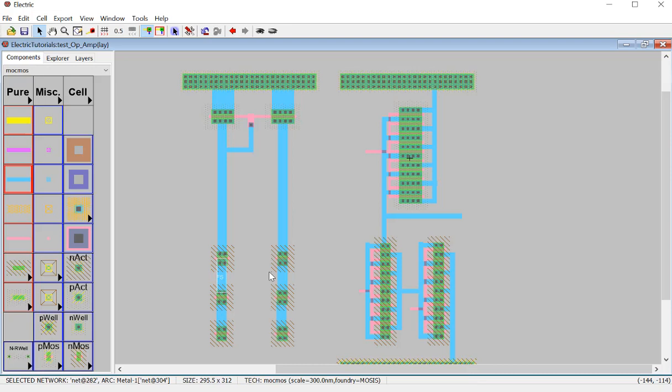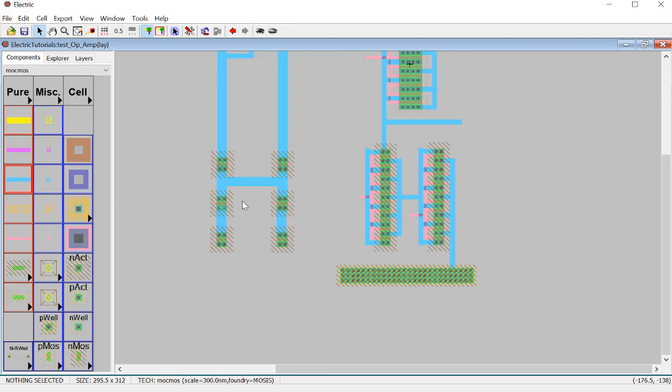And another thing you need to know is because these are the differential pairs, so that's a VS. So you want to short these two pins together. And these are the current mirrors. So you need to know what these ones are. And this one is actually being shorted to this guy because that's a V bias 3. And these two are being shorted together as well. And this is being shorted to V bias 4.